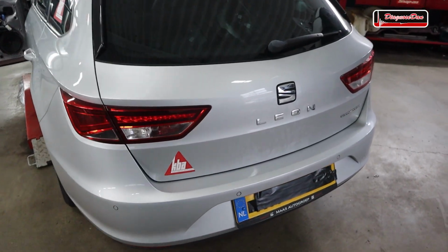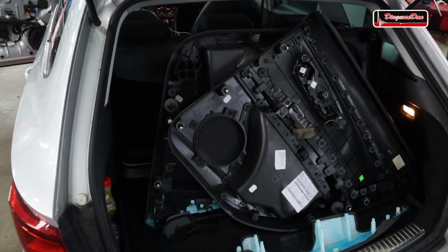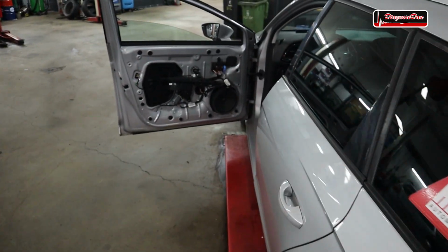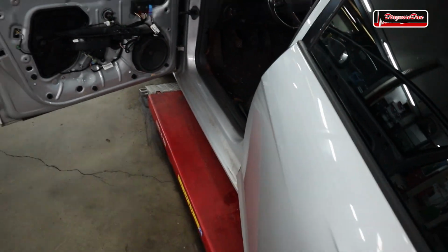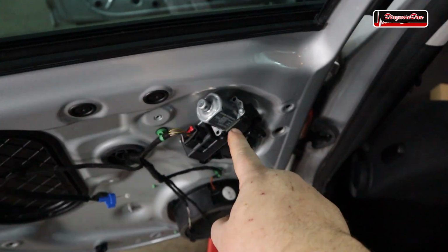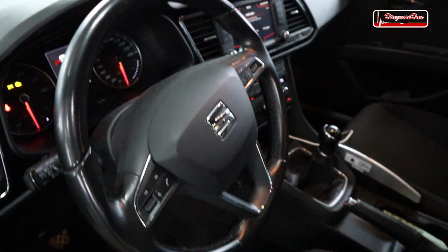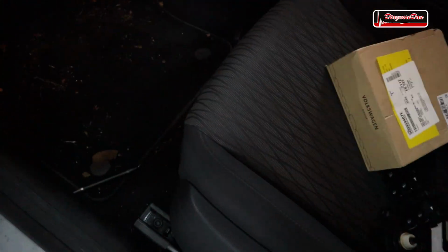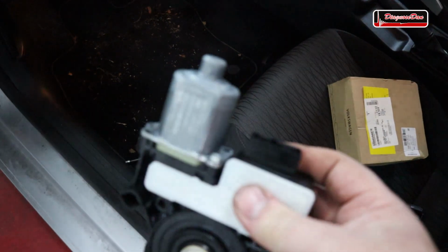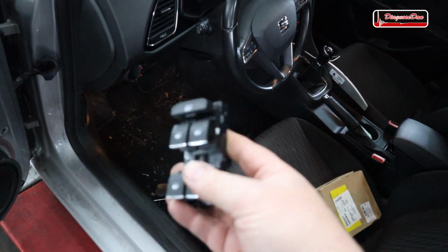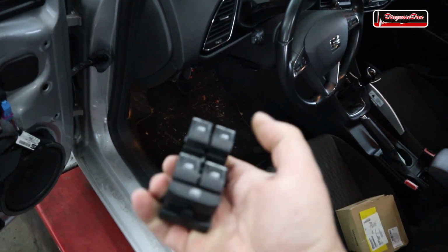Now, as always, let's start out by confirming the customer complaint. The other shop obviously already took the door panels off. They're in the rear of the vehicle. I asked them to leave them off for easy accessibility. The window motor that has been replaced right there is an OE one. It was purchased from Volkswagen. Now this is a Seat, which is basically a Volkswagen. This is the old unit. It is a window motor with a module, and they already also hooked up another switch block, but still no joy.